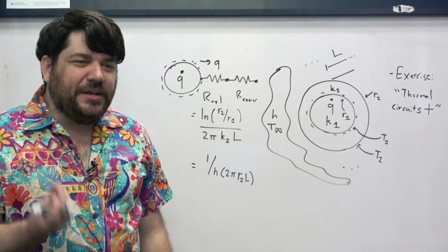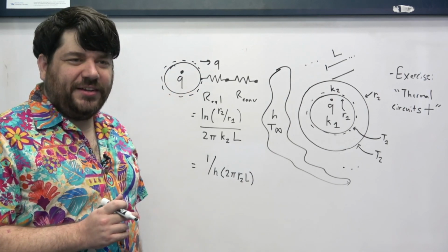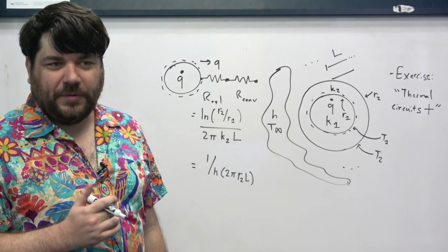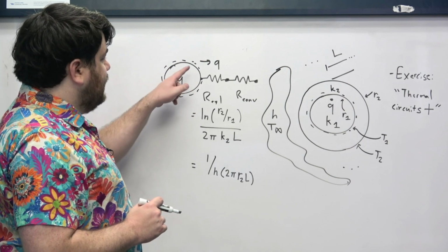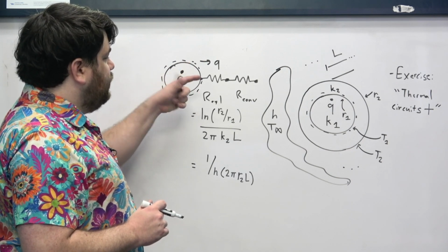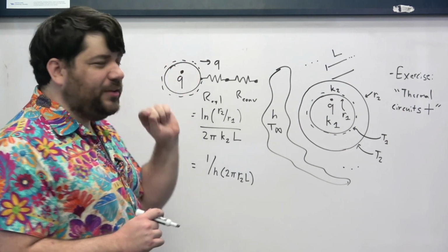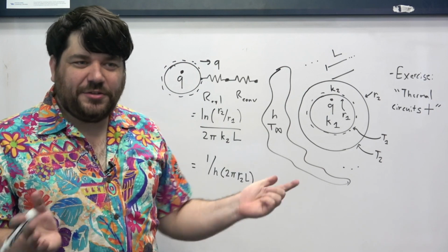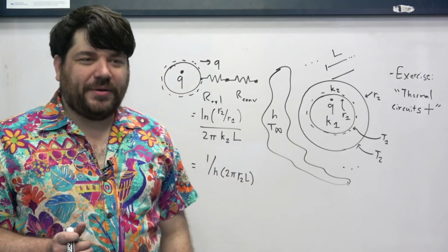Why? Because we know from energy balancing that if this system is in steady state, the thermal energy of the rod can't change over time, right? And we also know that because the system is in steady state, the only thing that can contribute to this outwards heat transfer rate is an energy generation term.